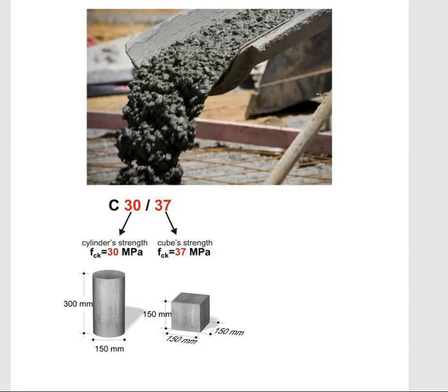Concrete strength is normally measured at 28 days. Why is this? Do you know why we test it at 28 days? Because concrete continues to get stronger with time, and 28 days is a common standard point used all around the world.